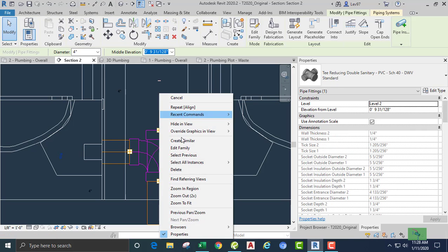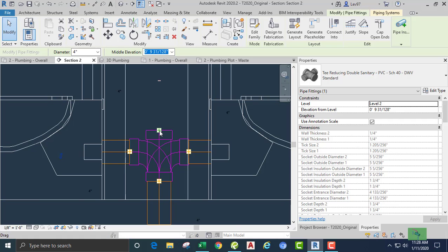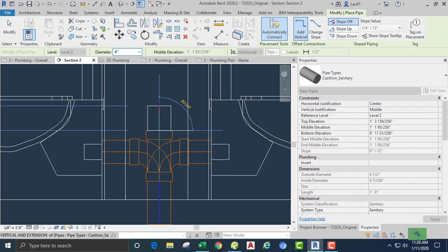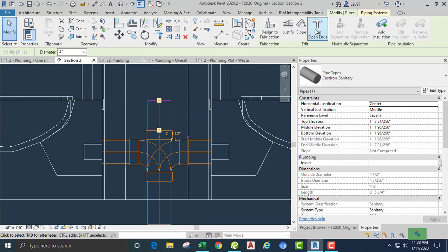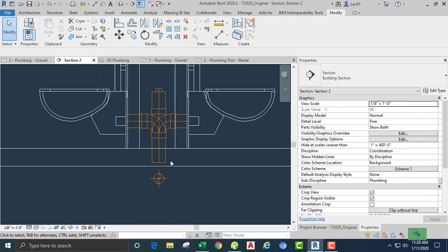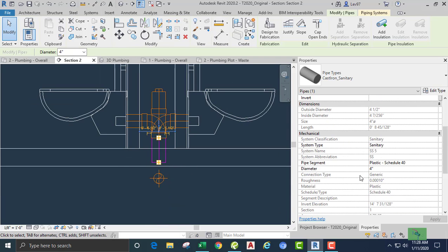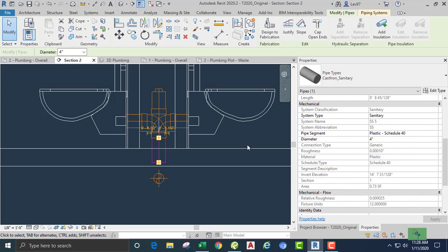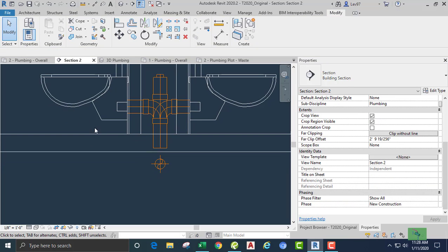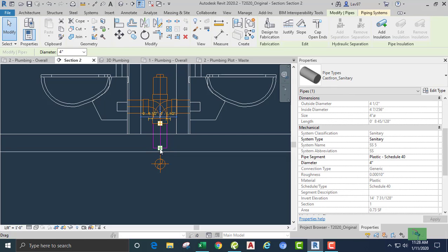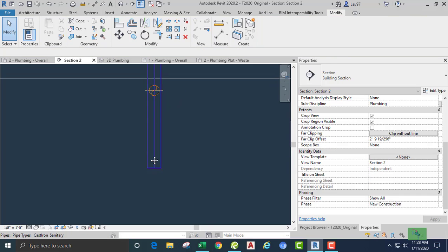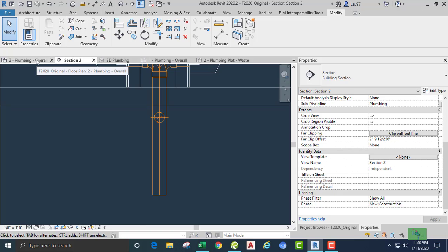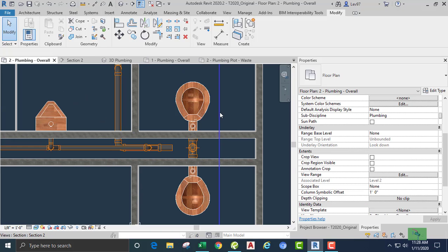Okay, so that we can draw our pipe. Let's cap this guy. Make sure that we are populating our fixture units. So it's 6 each. Okay, I'm going to go past the 3-inch, because we're going to connect into that guy. All right, let's go back. Okay, and rotate.